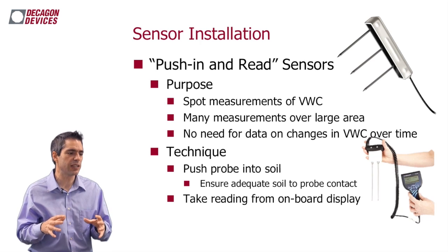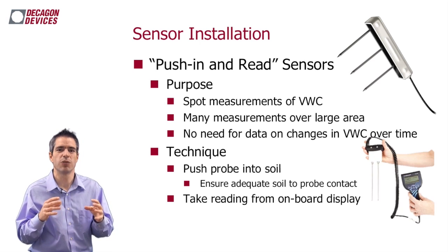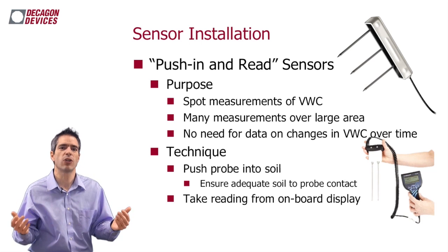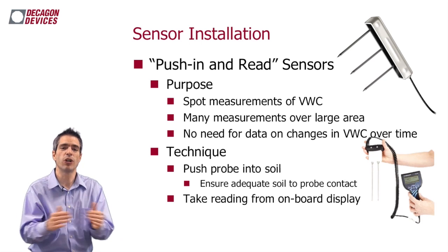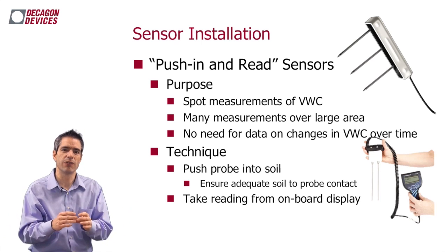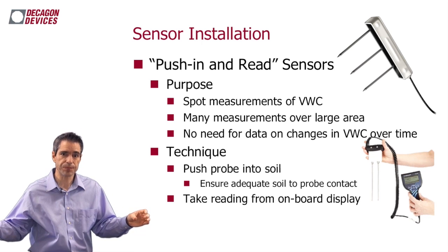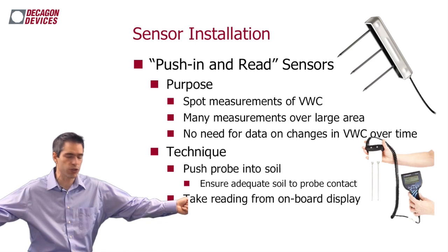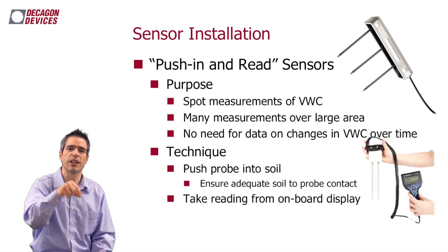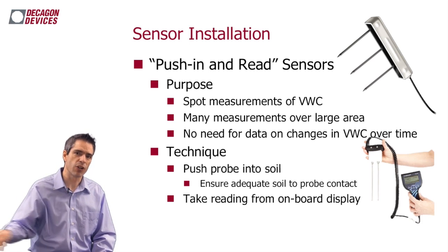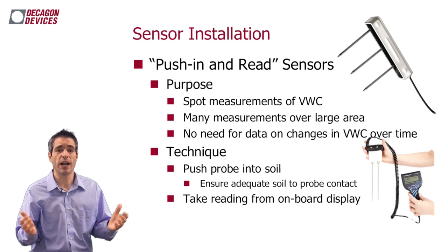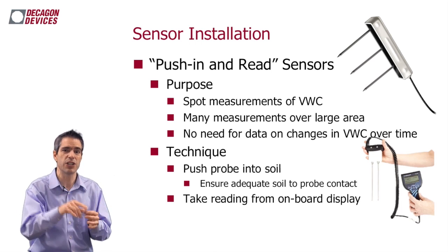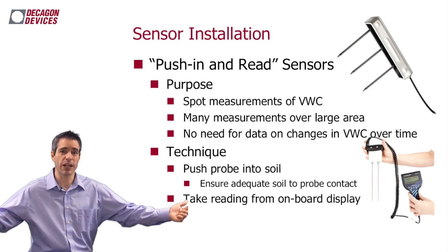My concern with this technique is not the way the measurement is made, but just the validity of that measurement. We spent a lot of time here just having fun looking at how water content varies in space. In fact, if you go out, take a long tape measure, lay it out, and measure water content, let's say every half meter across a long transect, you'll find you can create a very interesting variogram, something that tells you the variation in water content across the length of this.